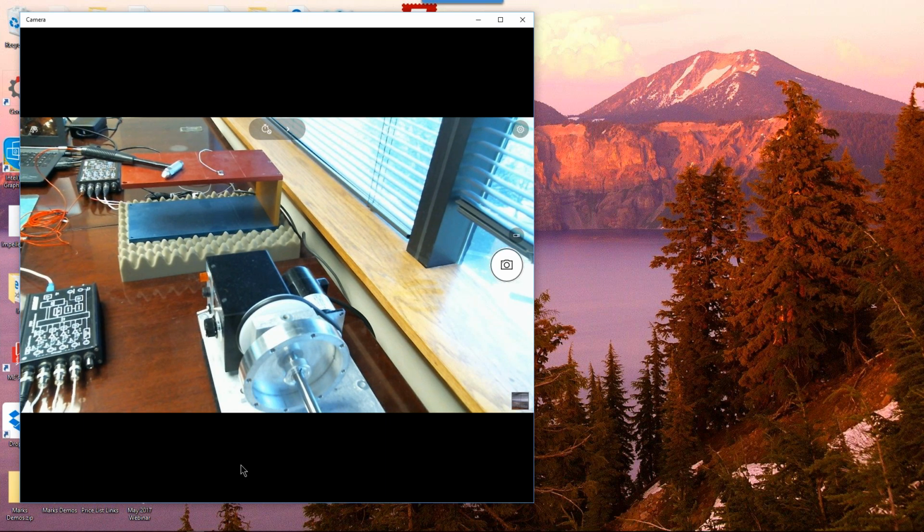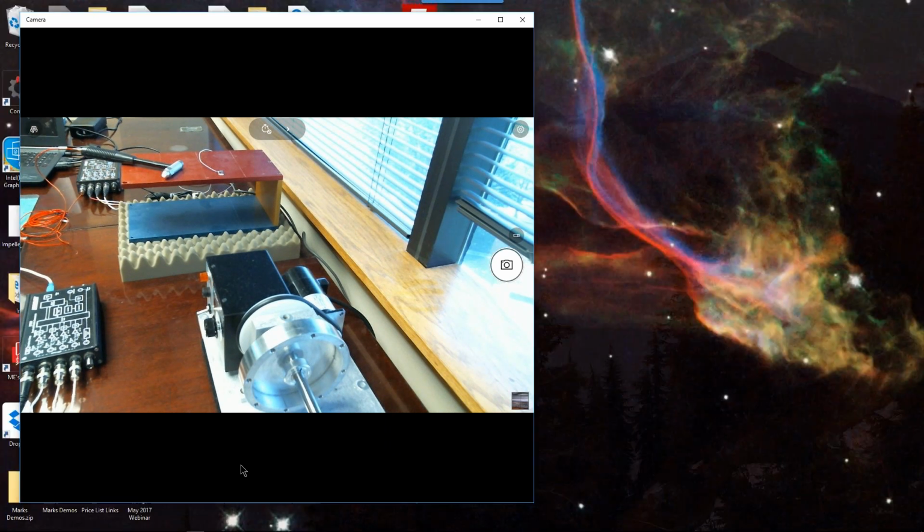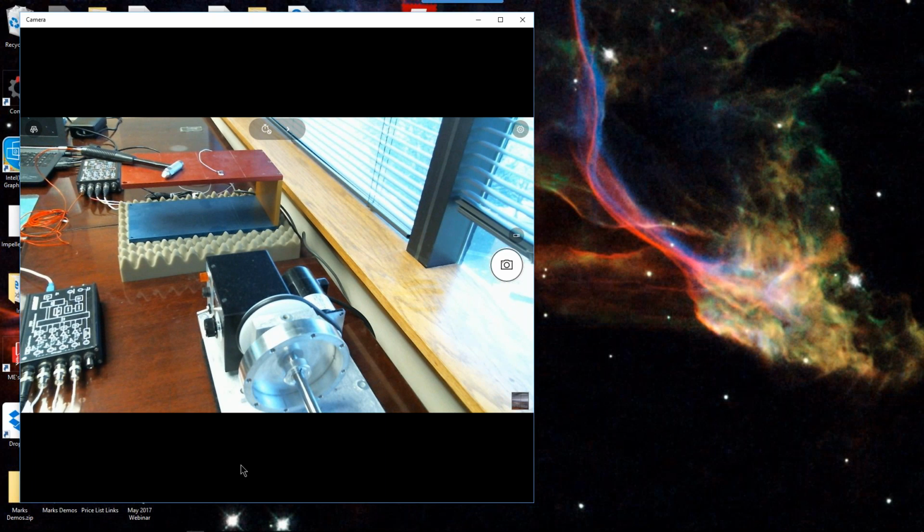Now, in the bottom of the picture is what Mark talked more about, and that is a rotor kit, and it's got some magnets on it. And so the second experiment we're going to do, and you can see the 4-channel analyzer that's attached to a triaxial accelerometer, and also the fourth channel is a laser tachometer. So we'll look at that experiment secondly, and I'll show you how repeatability can be used when we make measurements on a rotating piece of equipment like this.